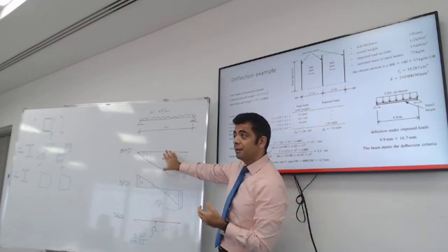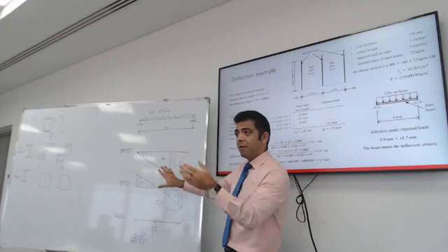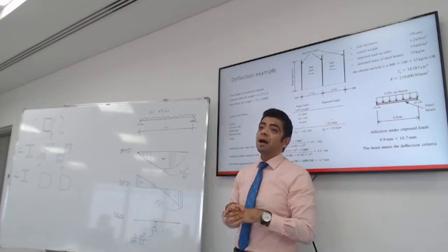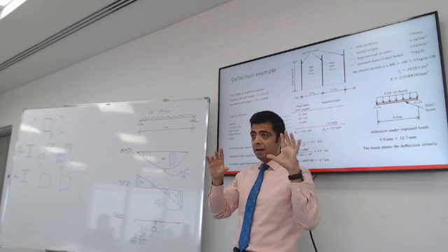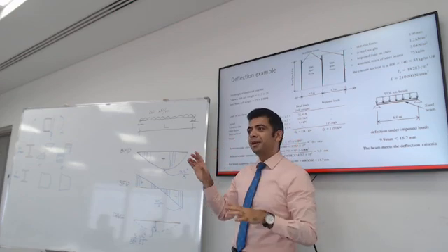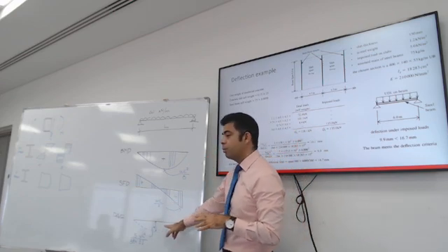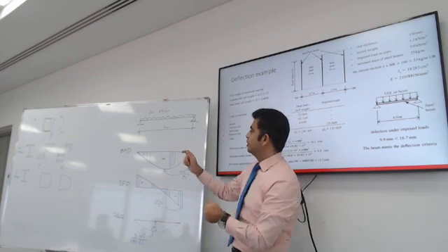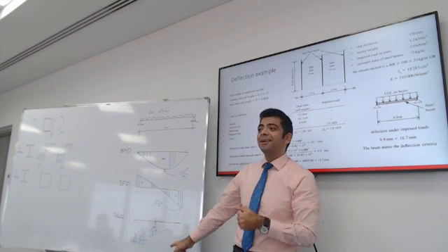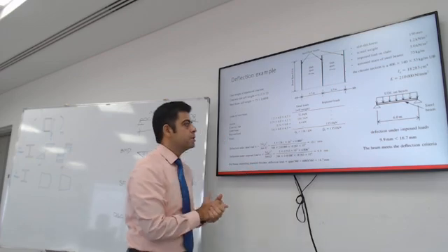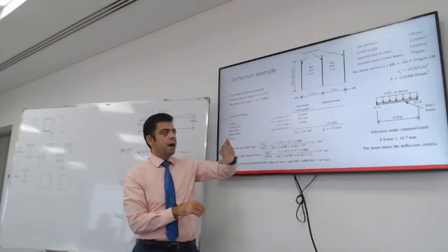From the design, you design the beam, and from the tables, like the commercial steel section tables, you choose a section that has a moment of inertia strong enough to resist bending, shear, and deflection. There you go. Okay, so here is the application.